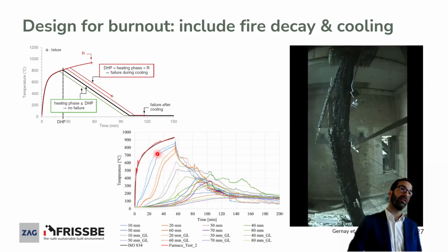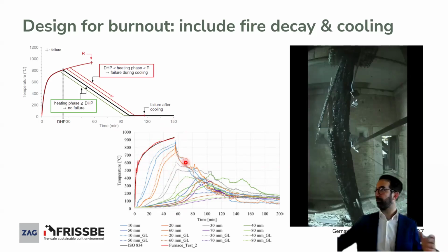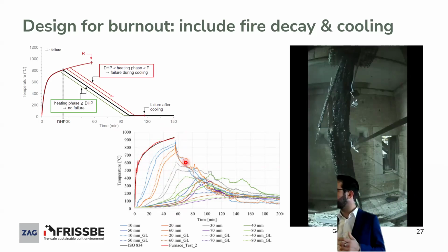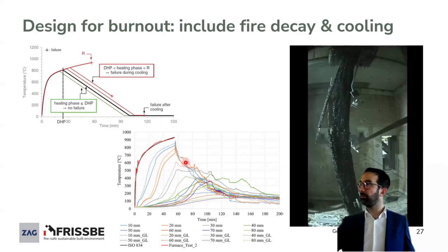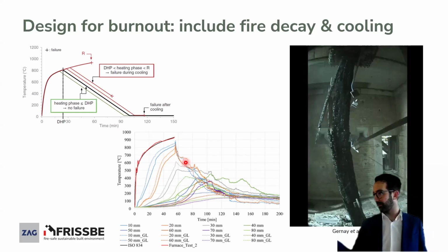And then what you can start to see is the gradient you have at the beginning, so you have the blue, orange, and gray, then at a certain point, the orange goes above the blue. So this means that the temperature of the surface, which was the highest during the fully developed phase of the fire, then cools down faster, while the temperatures more in depth, which were more protected during the fully developed phase of the fire, now become higher than the one close to the surface.